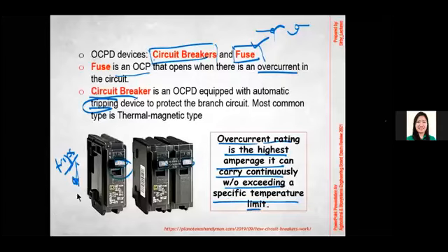So for example, if the branch circuit is for lighting outlets, there's a specified rating for typical applications, like maybe 15 amperes, and for convenience probably 20 amperes, although these are just some rules of thumb, but you also have to check it in the calculations as well.